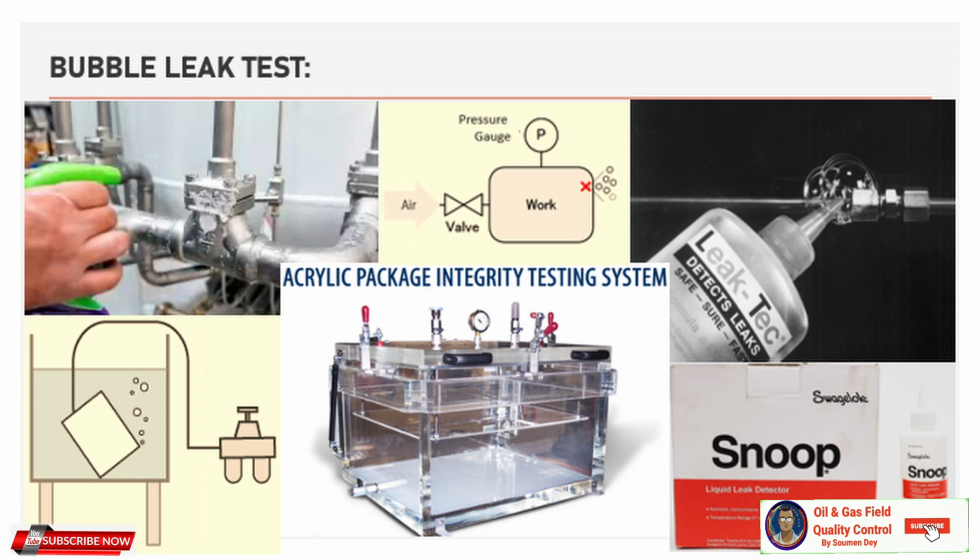Bubble leak testing takes significant time, is operator dependent, is susceptible to errors, and offers no data collection point. Bubble leak testing is usually a poor method for most leak testing applications, especially with a complex system.